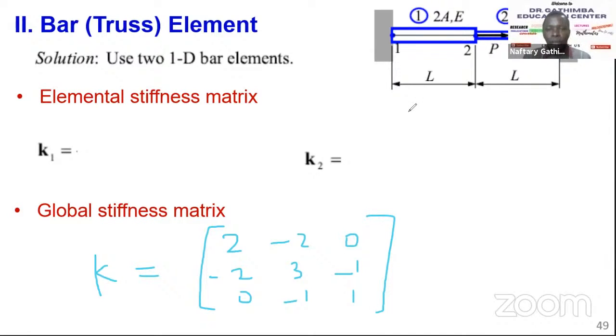When we come to the global finite element equation, you just need to introduce the force vector and the displacement vector. Remember, when we have assembled more than 2 elements, we are talking of the assembly at the global scale, the finite element equation of a structure, not of that element. So now you are not going to see the small f talking of the nodal forces, because we are talking of a combination of different elements. That's why we go directly to the global stiffness finite element equation.